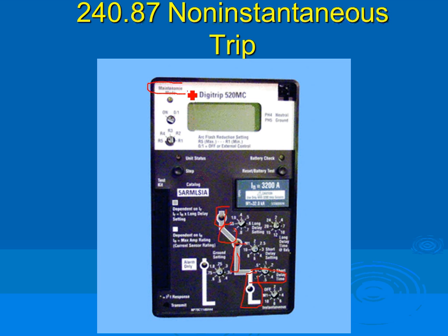It looks like here's a maintenance mode where you can plug this in and put the circuit breaker in maintenance mode, and turn the instantaneous on. In this case, you screw up your coordination while you are working on the system energized. You put your PPE on, of course, and you have to have a reason to work on it energized, like OSHA says in 70E.